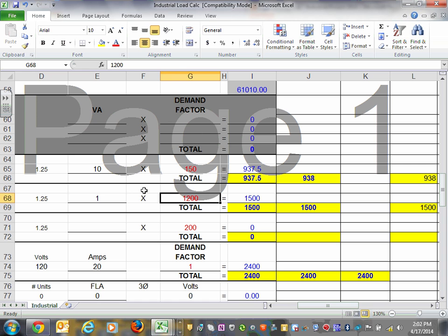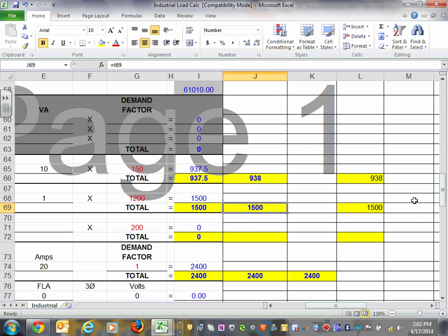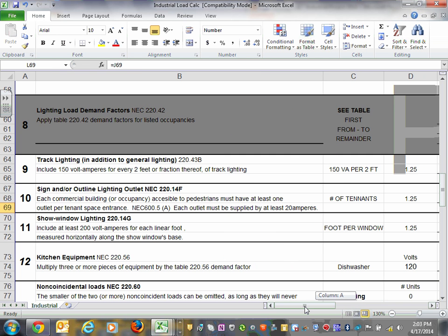We have one sign, a continuous load, and we put it under the switch gear, and this will be burning at 277. So I also put it under my lighting panel, because I'm going to take it out of my lighting panel. You could have taken it at 120 and taken it out of the receptacle panel, because you just splice it to wherever you want to feed it from, if your sign is 120. So this is a 277 sign, and we're going to pull it from there. So that's a couple of other loads that you can do, sign.